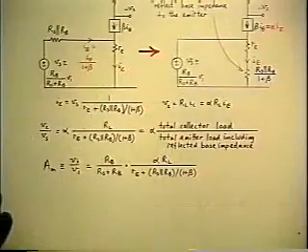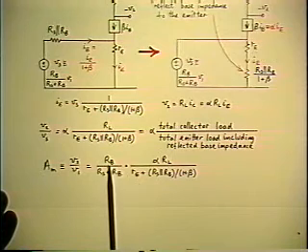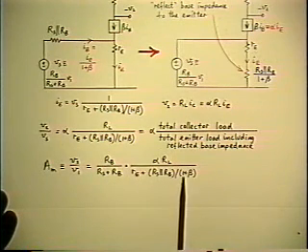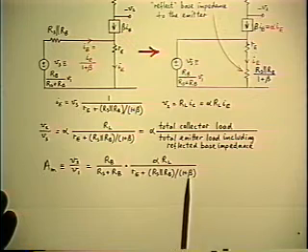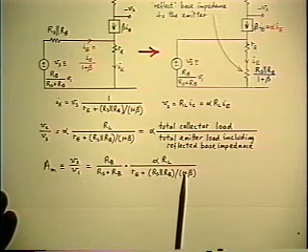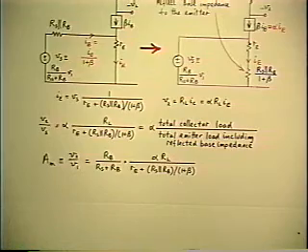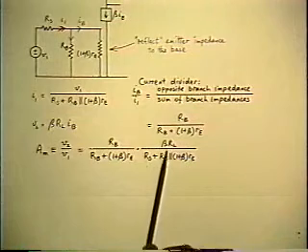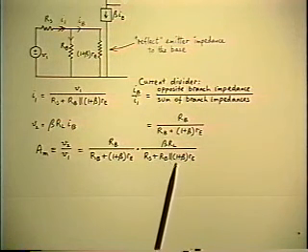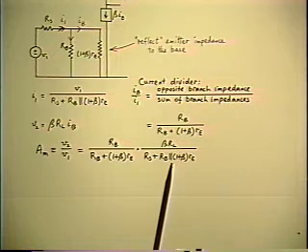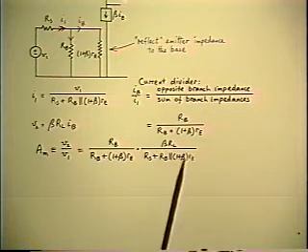Just as an example, looking at these two. This expression is already useful for telling you three more things. We talked about them already: divider ratio in front, series-parallel combination of resistors, sensitivity to beta. Those are the three direct pieces of information you get out of this one. That's fine. When might the other one be useful? This one obviously is not so good for looking at the sensitivity with respect to beta. Not good at all. See, the beta is in three different places.